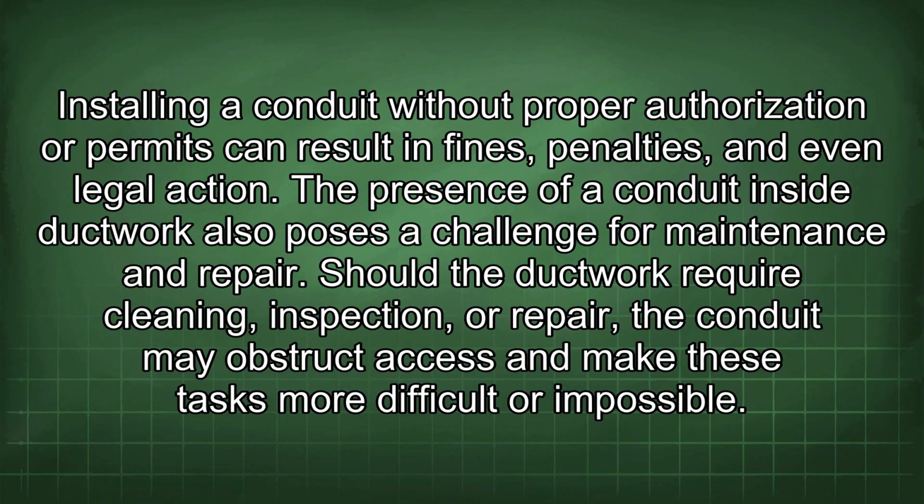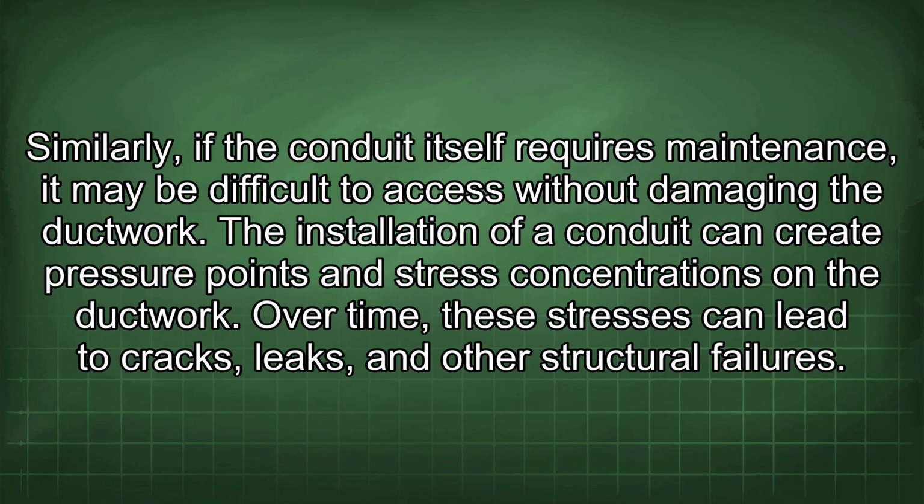The presence of a conduit inside ductwork also poses a challenge for maintenance and repair. Should the ductwork require cleaning, inspection, or repair, the conduit may obstruct access and make these tasks more difficult or impossible. Similarly, if the conduit itself requires maintenance, it may be difficult to access without damaging the ductwork.